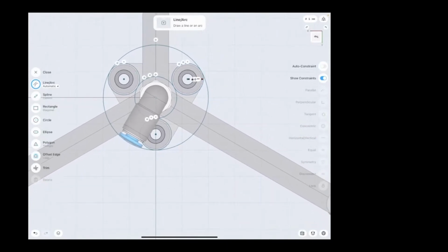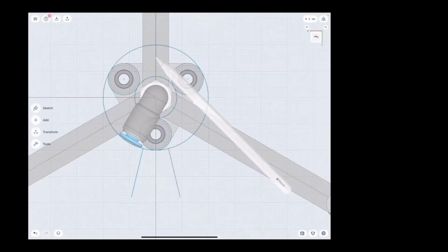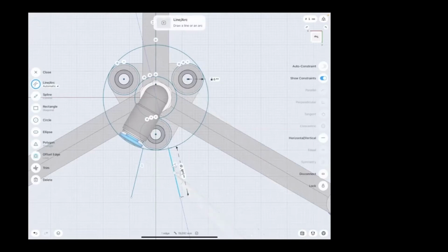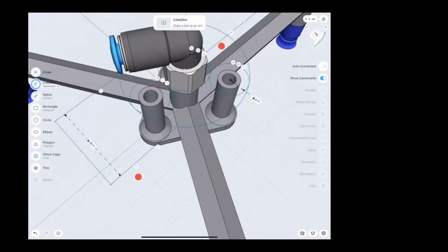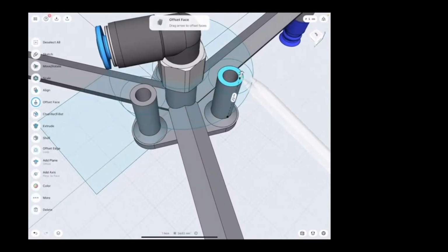I will need to create a small handle shape to this part. So let me just create 2 lines, constrain those to be symmetrical to a vertical edge, constrain them to be vertical by themselves, connect them and define the distance between these 2 lines. And then I can rotate away the view again, and I have a lot of cross-section to work with.